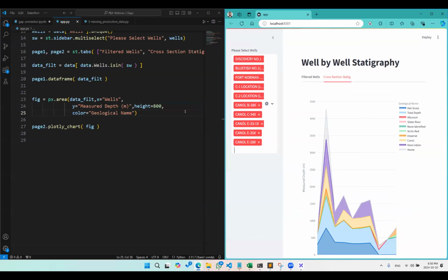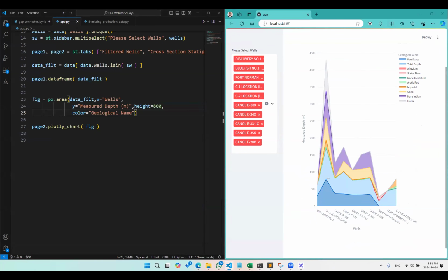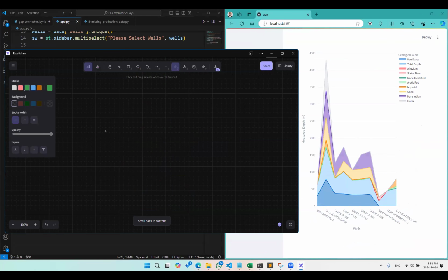One of the customizations that we usually do is the type of the line. The geological cross section can have 2 types of lines. For example, let's say that we have 3 wells, which will illustrate the example a little better, and we have penetrated the same layer at different depths. Now you have 2 options for plotting these. Either you connect these layers with a straight line, something like this.